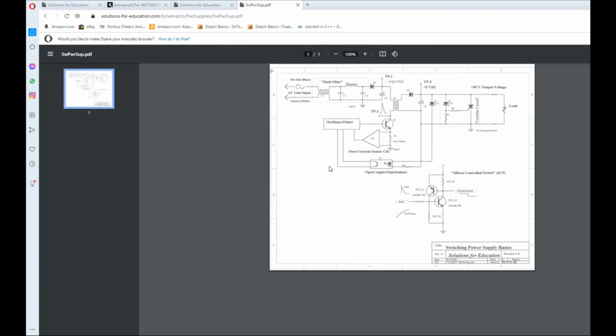So it starts off pumping this guy up, like an air compressor, if you will, pumping this guy up primary to secondary. And when the voltage gets up to where we want it to be, the LED passes on optically. So it's an opto coupler, an opto isolator, passing on to the oscillator pulsar circuit, and it says, hey, back off, hold it right there, don't go any faster, and therefore it can cause this guy here to increase frequency or decrease frequency.